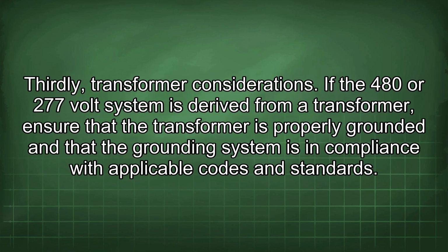Thirdly, transformer considerations. If the 480 or 277 volt system is derived from a transformer, ensure that the transformer is properly grounded and that the grounding system is in compliance with applicable codes and standards.